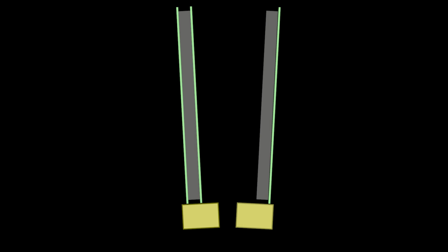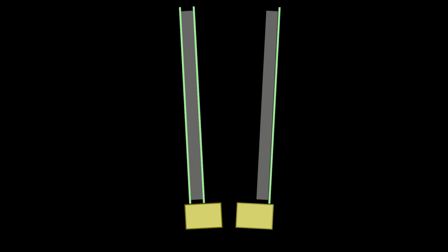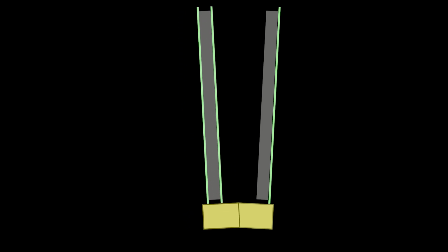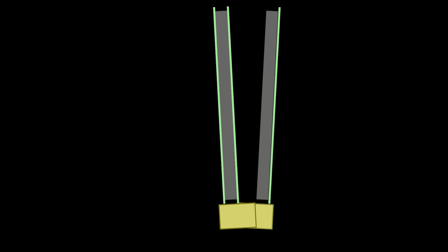When this happens, it will cause the glass on the fixed table to tip and fall over. Therefore, we need to determine the maximum safe distance that the moving table can traverse in, and then we need to set the max shifter stroke parameter equal to that position. Once this is done, the table position will be dynamically set to accommodate various unit thicknesses, as long as the shift cylinder does not exceed the max shifter stroke.